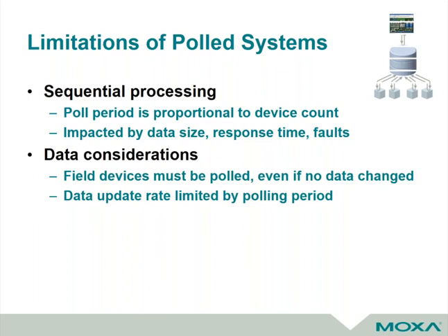You also need to think about this: when you do a DNP3 or Modbus application, you're always polling that data whether it's changed or not. If I'm looking at a lift station on a wastewater application, and the level height for the well has not changed in the last 15 minutes, I'm going to poll it regardless. I have no way to work around that.